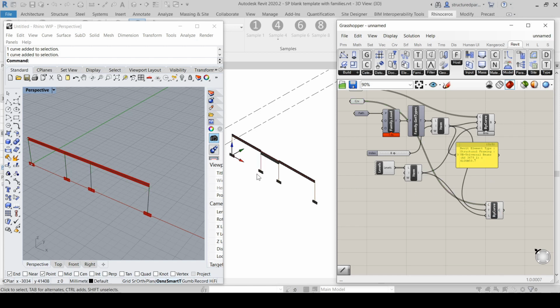So it's got really confused. And the reason is beams, although they can have a slant, it's not seeing them as columns. As I said before, Revit thinks of things in beams, and columns actually have a whole different set of properties than beams. So you have to do things a bit different.